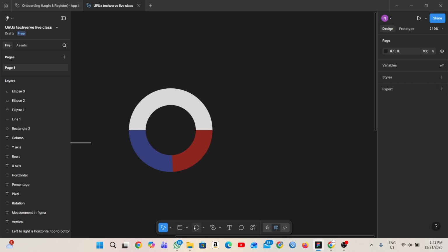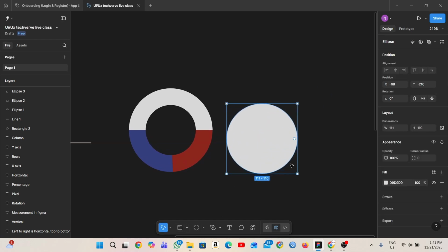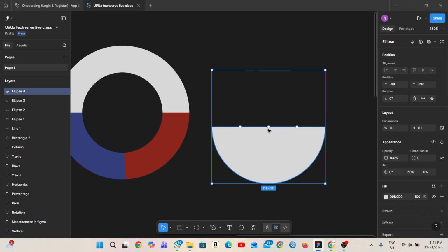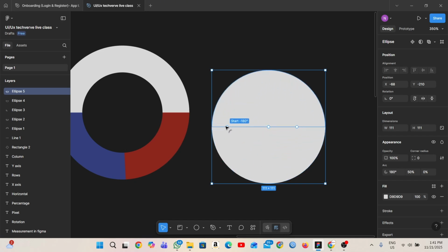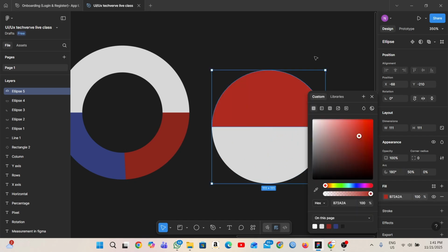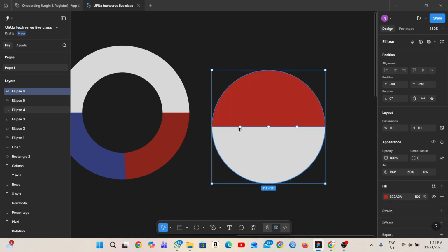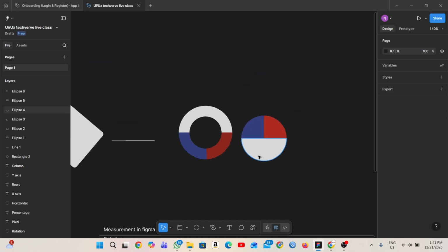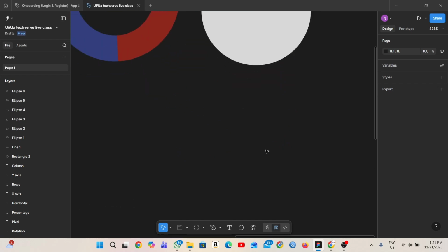Sometimes too, you might not really want to expand your radius, right? So you might just do your arc like this. Sweep, make sure it's 50, and then Control D and you start, right? You bring it up. You have something like this. Control D. Remember it's from your start and you sweep rather. So we have something like this. You must not do this whole. It depends on what you want to achieve with your ellipse.